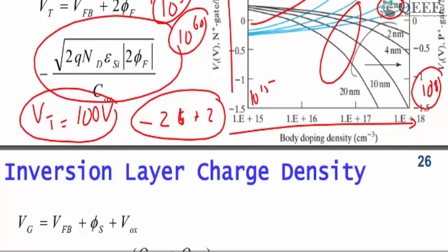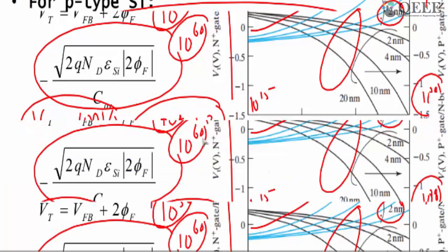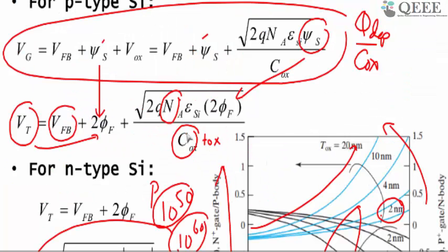There is another question: if we take two different materials for the gate oxide, is there an influence? Do you mean two different devices, or mixing materials in the gate oxide? The influence of the gate oxide comes through the COX term, which in this case is epsilon ox by T ox. So if you change the material, the question is whether you are changing the gate insulator while fixing T ox, or only changing the dielectric constant.